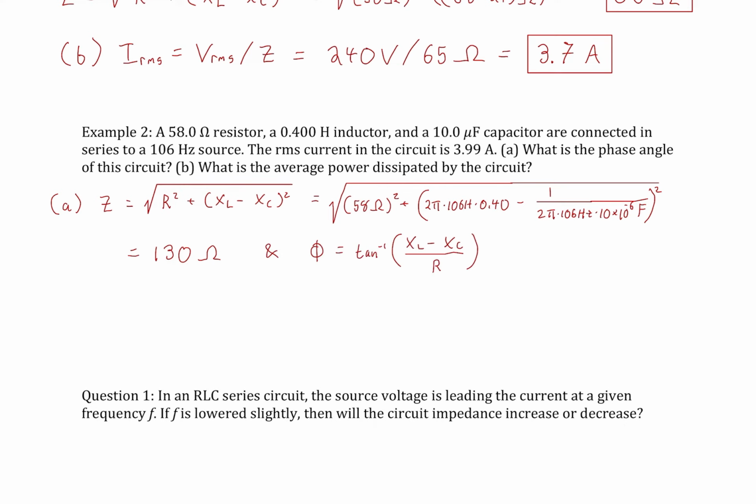And now we're going to use the phase angle formula that says that tangent of phi is this expression here, and then we're just going to solve for phi. So here I'm just combining everything. And I did this in a not very straightforward way, because I found the reactance, obviously, and then plugged it in here, but I don't show that calculation. So there's some back and forth work, but regardless, here we have the reactance of the inductor and the reactance of the capacitor, and we're just taking the tangent inverse of that ratio. And that gives us a phase angle of 77 degrees.